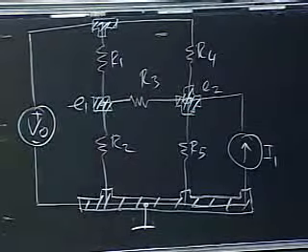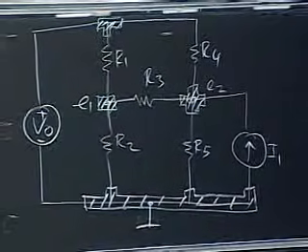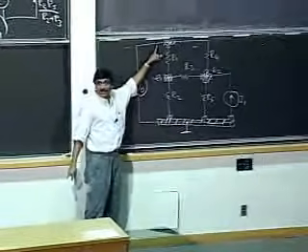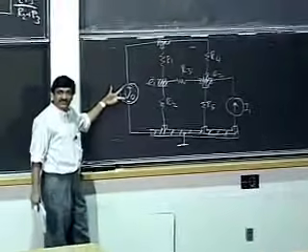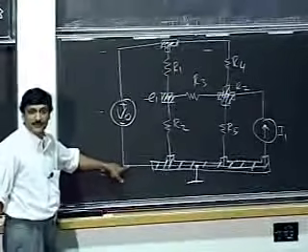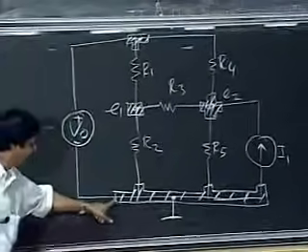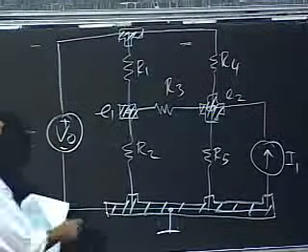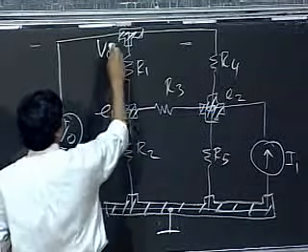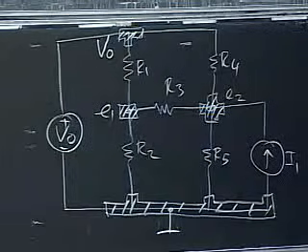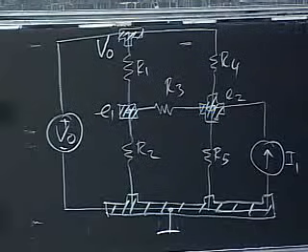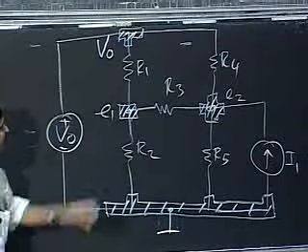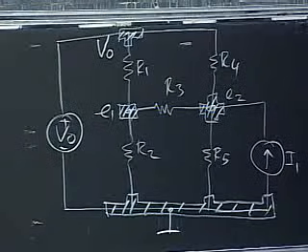What about this one here? Is that voltage unknown? No, I know what the voltage is because I know that this node is at a voltage V0 higher than the ground node. Okay? Notice that to go from here to here, I directly go through a voltage source, and so this node has voltage V0, and I'll simply write down V0. Okay? If you try to simplify the number of steps that you have to go through, directly go ahead and write down the voltage V0 for that node.